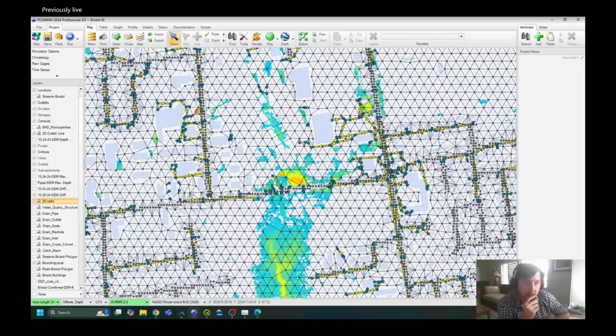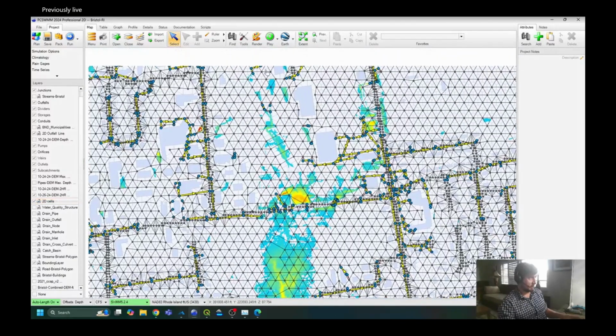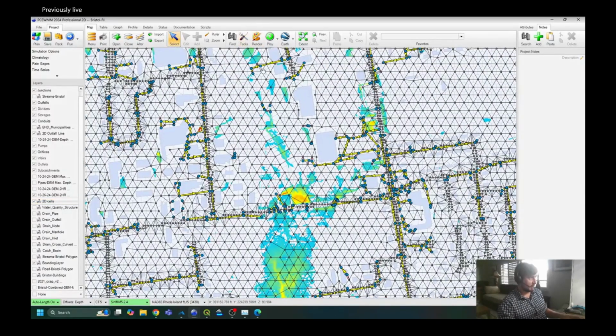How sensitive is the rain on grid peak flow and runoff values to the mesh resolution? How do we select the most appropriate mesh size for rain on grid for practical applications in urban areas? Well, if you use the subcatchment area, this would represent the area in which rain was falling, as opposed to if you use this new tool that again is coming out in a week, it's going to be the resolution of this. How do you decide what resolution to use for rain on grid?